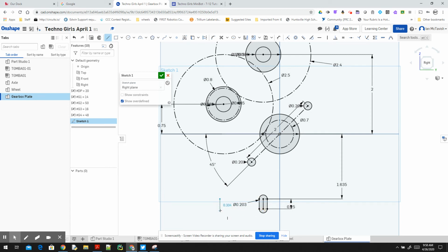And I'm using a technique that I find really useful so that way I don't need to force the length at all. This point is horizontally constrained and this point is horizontally constrained. Do it on the other side so you can see. So I start and just move over, click, and now I'm just going to move over to that point, and you can see I've got my dotted lines, so everything is constrained, so I don't need to worry about the measurement. They're perfectly lined up.